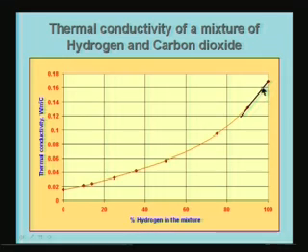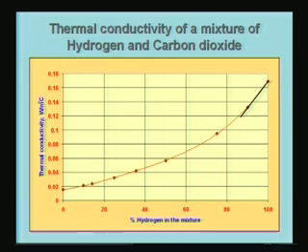Okay. If it is 95%, that means 5% CO2. So, the thermal conductivity comes down very slightly. That means that the resistance or the temperature is going to change by a small amount, and if we have sensitive detection, we can determine or detect this temperature difference in terms of a change in the resistance, okay, as we were talking about earlier, and this change in resistance can be monitored and related to the concentration of the CO2 in the mixture.